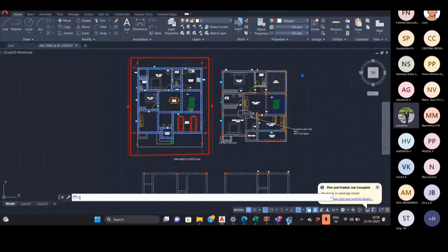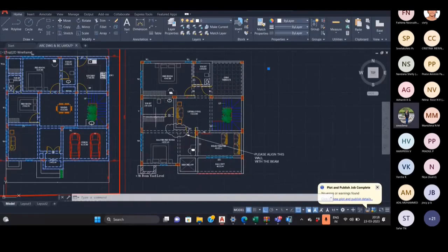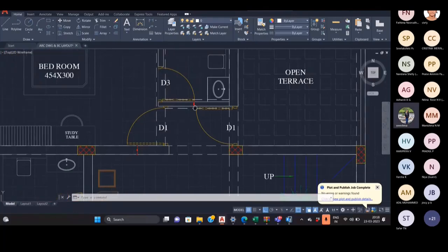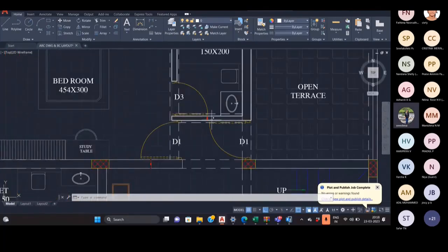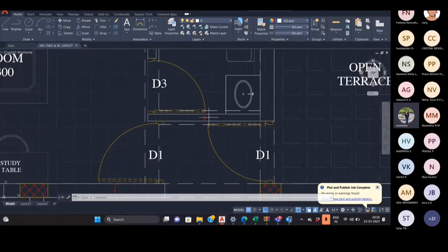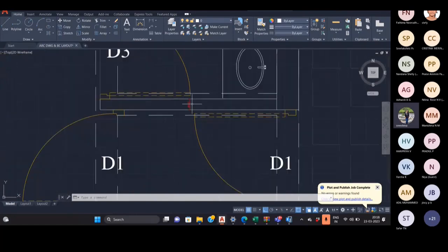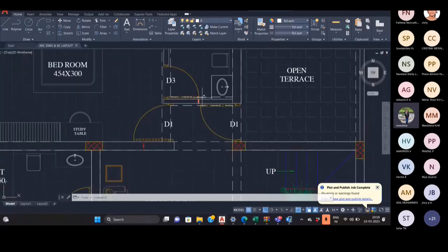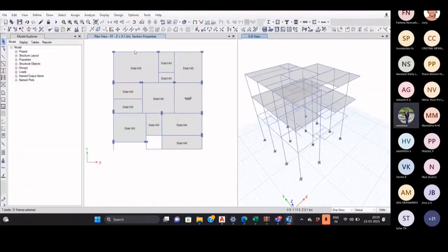In the next floor also there is a wall on every beam, but we can see that this wall thickness is different from the others because it is a partition wall. Its thickness is 99.7, which is almost 100 mm. So its thickness is less, and the load acting on this beam will also be different. So we don't need to select it for this load. We can select all other beams except that.